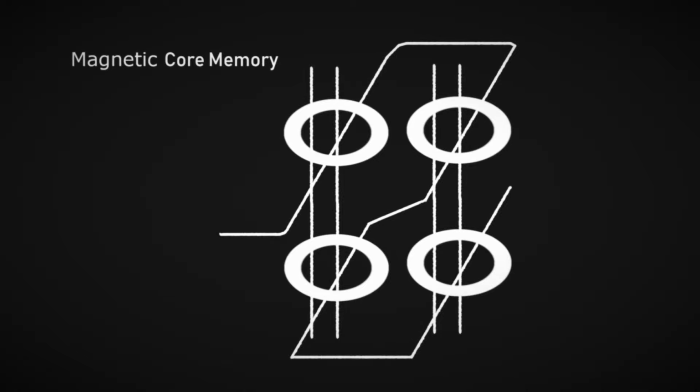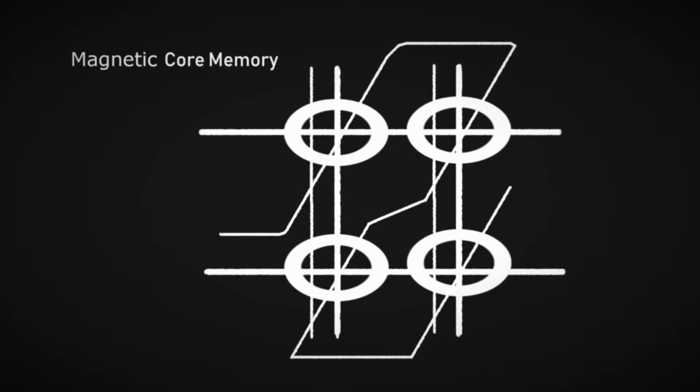Next, a modification of the select lines is needed. If we did apply a current to one of them, all the cores in a row would be magnetized at once. To overcome this problem, we add vertical select lines to the array and split the current needed to change its magnetization in half. Now a single selection line is too weak to magnetize a core. By this, we can select the core we want to read out by the crossing point of the selected vertical and horizontal selection lines. This is also the reason why this type of memory is called coincident current core memory.